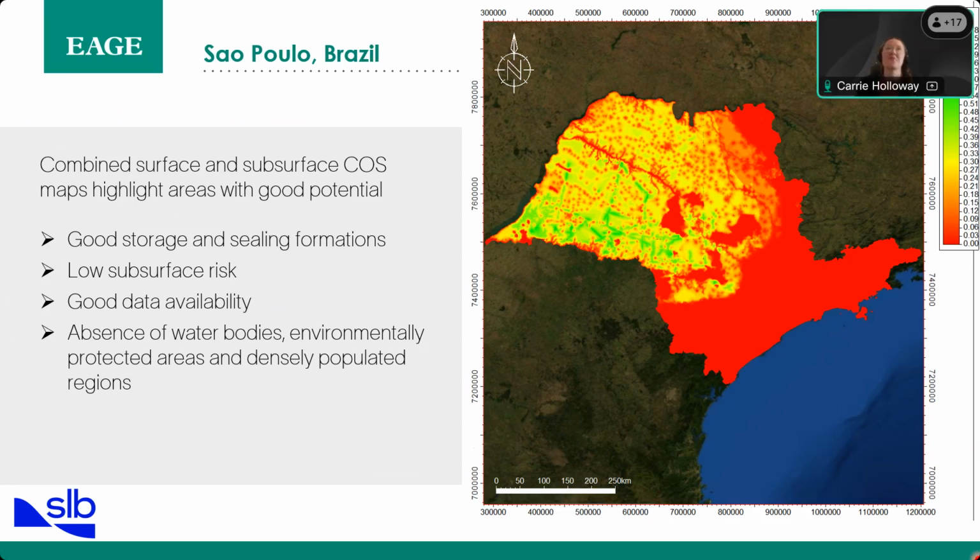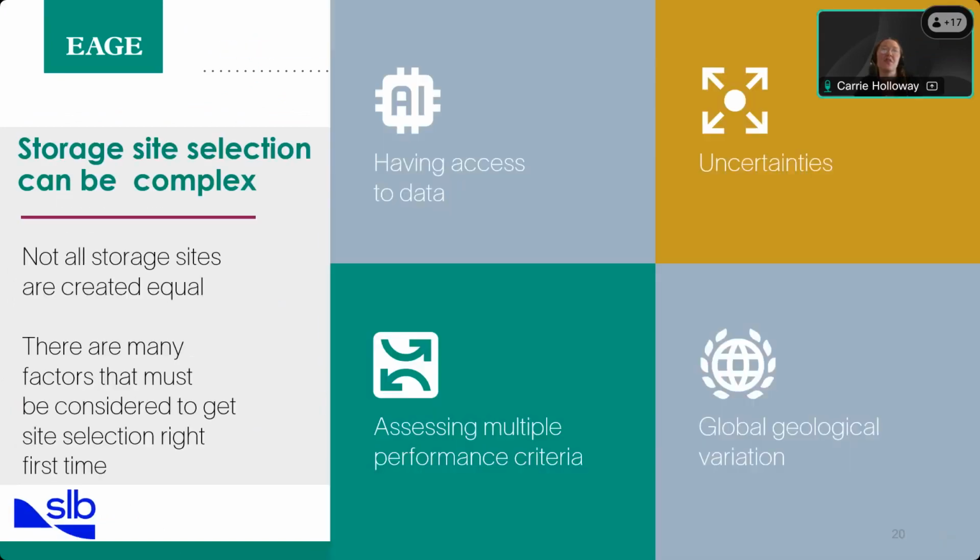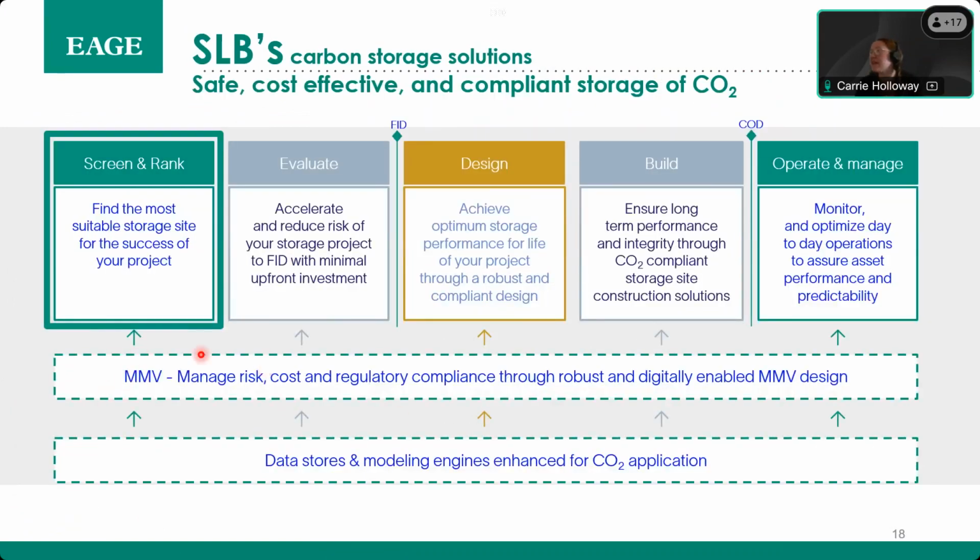Okay, so I didn't talk much about the monitoring plan. It is considered at all stages along a project. This is the MMV. So in terms of the strategies, it depends on the project, but we need to have monitoring wells, and these are wells that are monitoring both the injection formation and also higher formations, so that we can actually take pressure measurements and measure the presence of CO2 at a distance from where we're injecting.